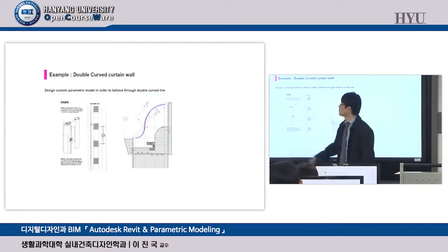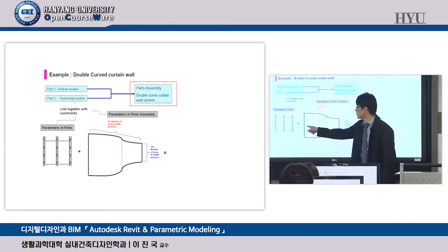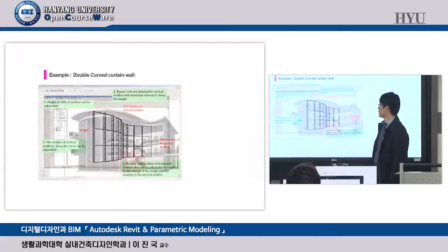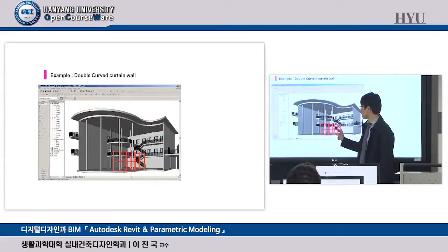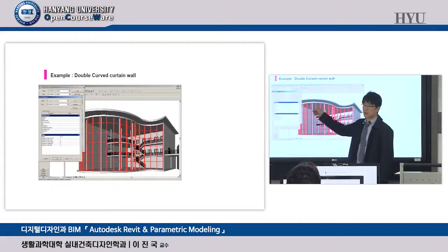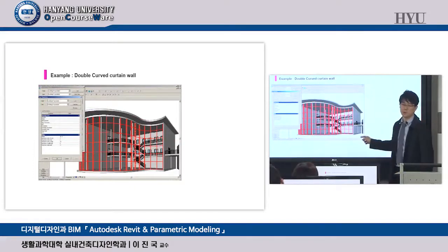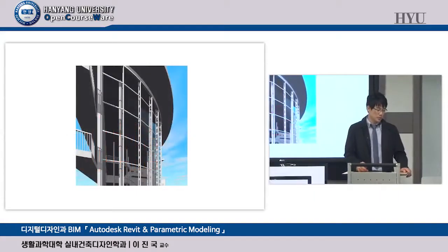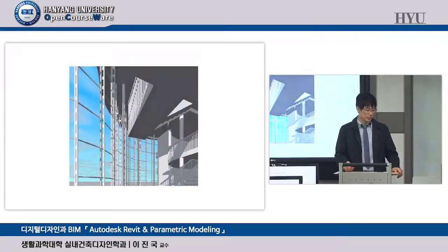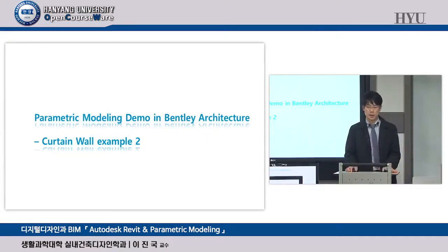And this Kawneer truss wall system is defined by the Revit Family Editor in this way and installed on this assembly surface like this, okay? Height and number of vertical mullions. So installing this truss wall system in a Revit project like this, okay? Making its height appropriate, and the geometric shape follows the arc line. So this is the Revit render output from 11 years ago, okay? Another render from the interior. And the next example, we'll see after the break, okay?